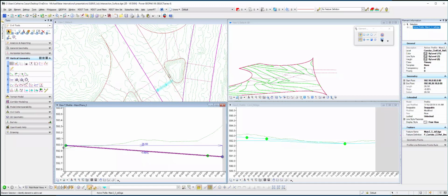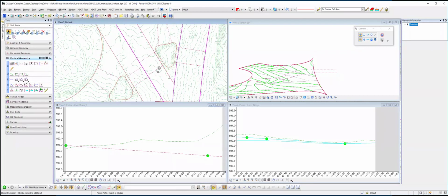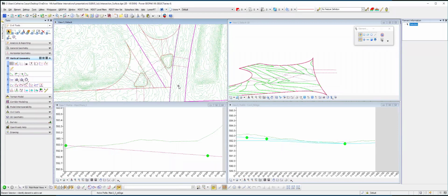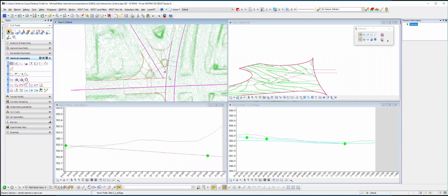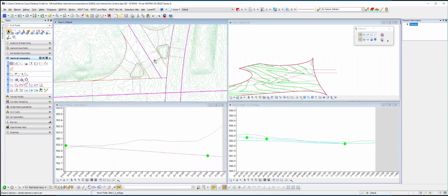I'm warping the pavement to flatten it out as I come to this large open space of pavement where the vehicles are typically not turning. They are turning onto the main line, but they won't be making this maneuver at all. The vehicles are really just making the maneuver from southbound onto this leg here in the one-way direction.